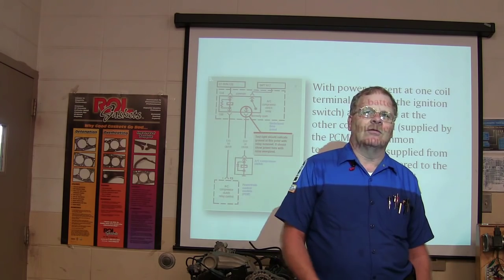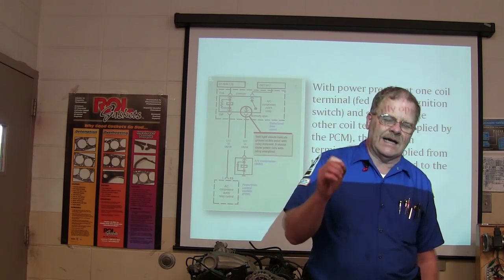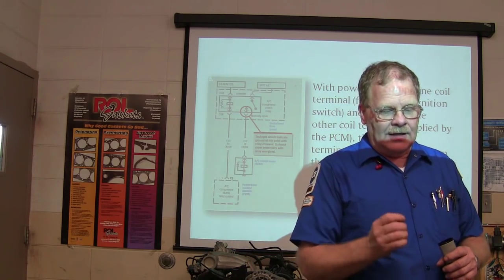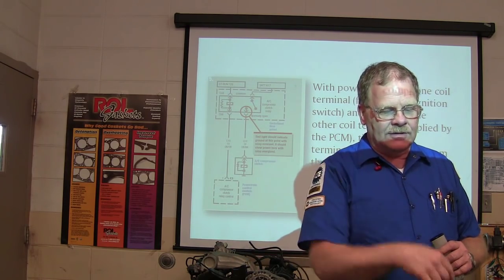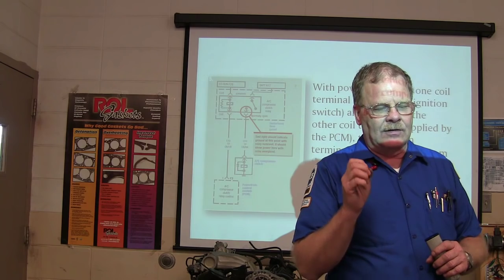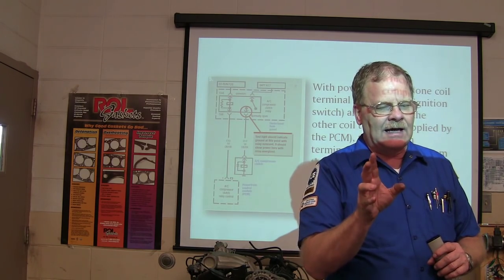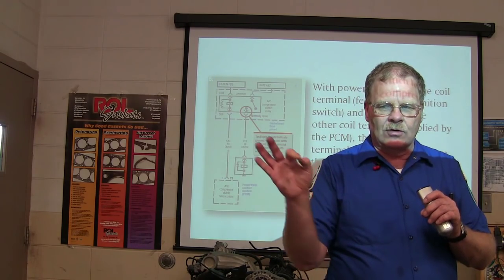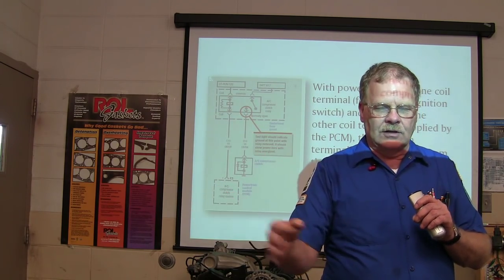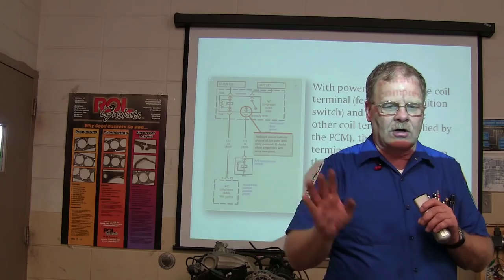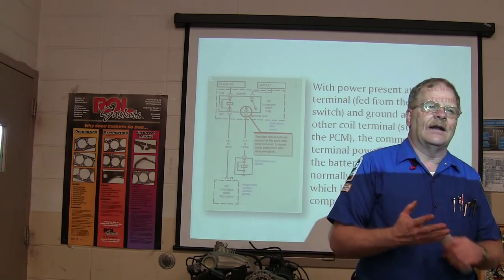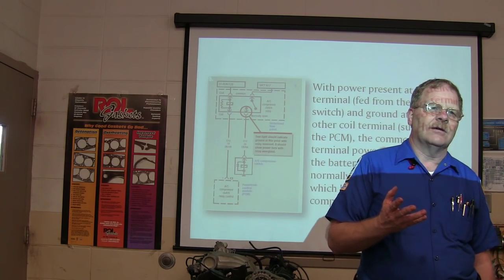And so anyway, she brought it over here. What I did was I took my test light and hooked it to power, and first I hooked it to ground, and then I went into that wire that goes down to the compressor, and whenever we turned on the AC, that light fired up. I said, okay, that's interesting. So I left the test light where it was, switched everything off, turned the car off, and moved the lead over to the hot side of the battery, and the light did not light up. You understand what that means?